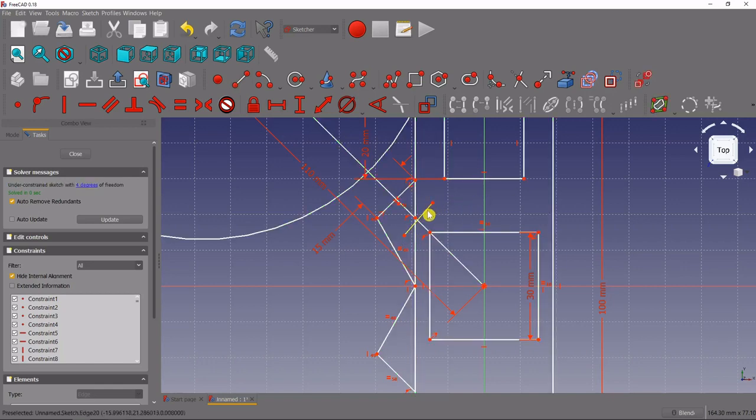And we first want to make this line perpendicular to our arm, so we'll use a perpendicular constraint for that. We also want it to be symmetric about the arm, so we'll select the two endpoints, select our arm line last, and use the symmetric constraint. Then we want to fix it onto the point. We'll select the line, select the point that we drew, and fix it onto there.